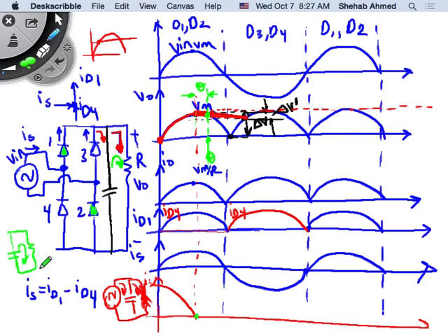You can solve for current with a first order differential equation. The solution for the current is A e to the minus t over tau, so it's an exponential equation. We have the expression for this exponential until a certain point. A certain point where what happens? Where the supply voltage is now higher than the capacitor voltage. If the supply voltage becomes higher than the capacitor voltage, then diodes 3 and 4 will again start conducting in the second half cycle. And we repeat the cycle.